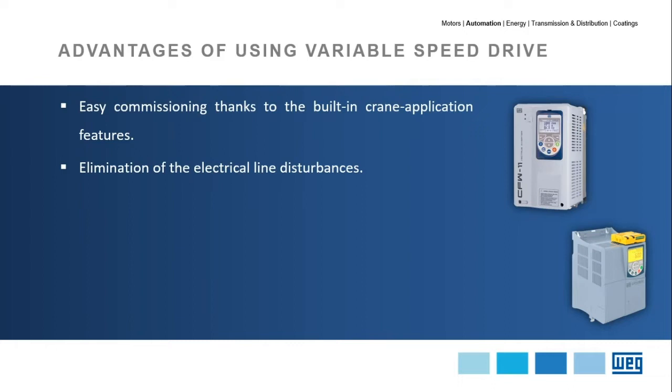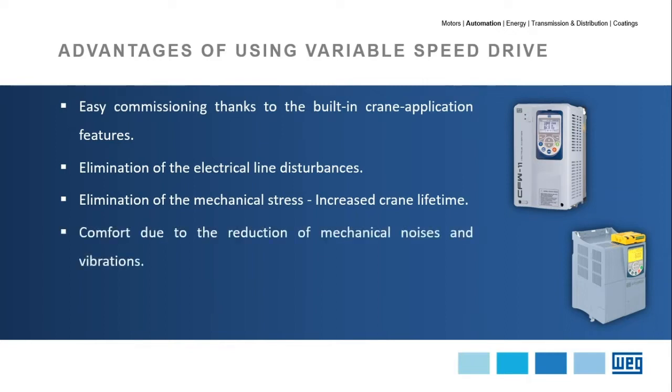Elimination of electrical line disturbance. Since the VSD can control the motor torque, the starting current of the motor will be reduced as well, which will also eliminate this line disturbance. Elimination of mechanical stress, and here we need to point out that it will have increased crane lifetime. Comfort due to the reduction of mechanical noises and vibrations to the system. Energy saving: again, the VSD can control the motor speed and therefore energy saving will be achieved.